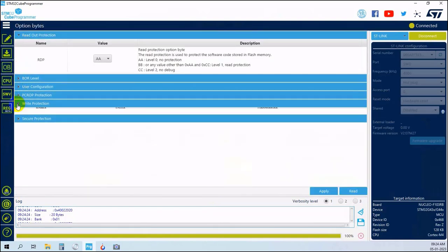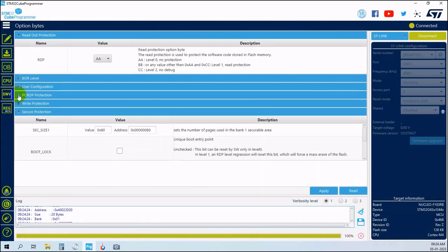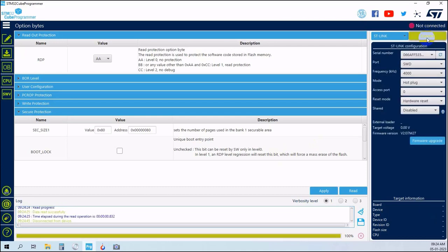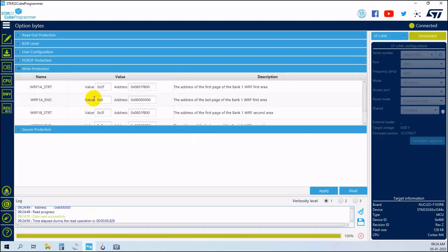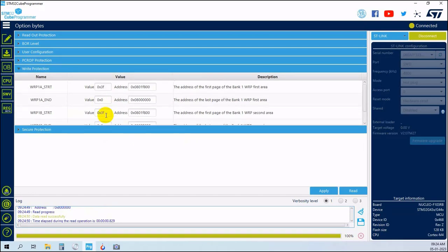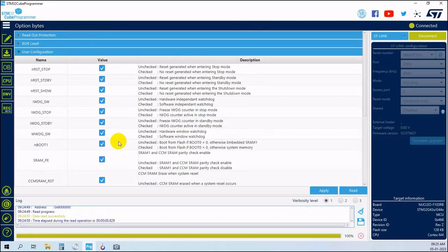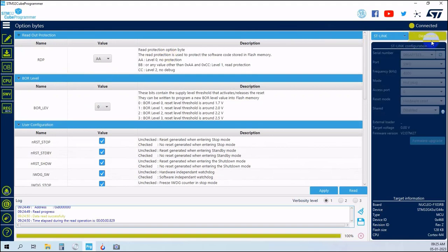And these are the option bytes that are there, right? This also has been programmed. So I did not change it in the previous settings. Maybe I can change these settings also. So let's change these settings also. So if you see here, let's say write protection, this is 3F or some values are there. I can change these settings and I can verify all bits are set by default here. I can change them and I can verify whether it is working or not.